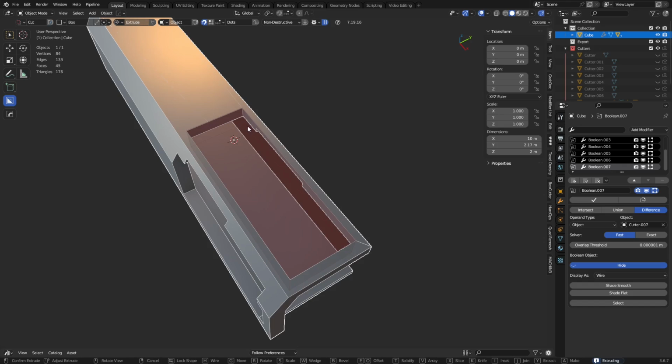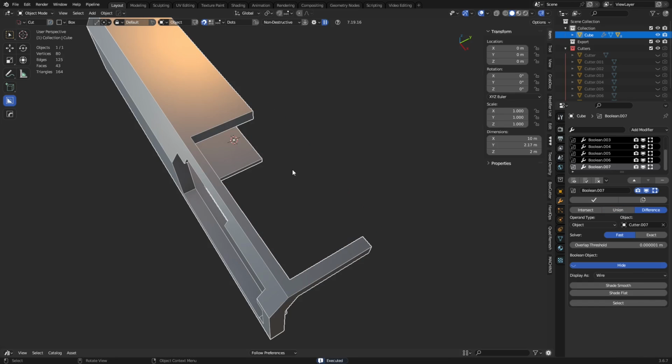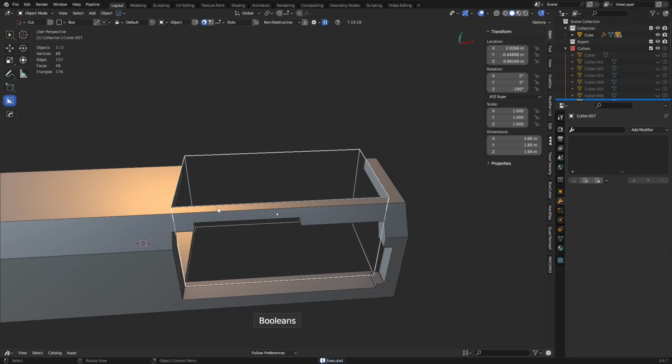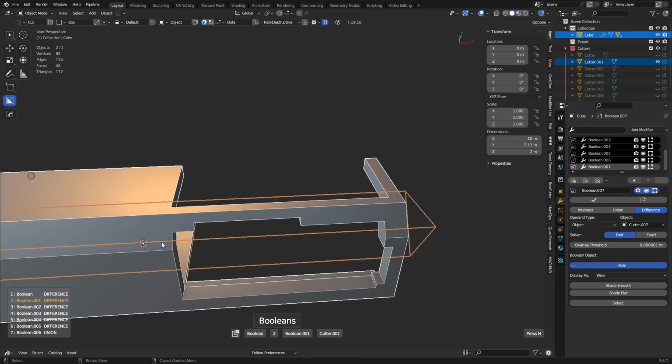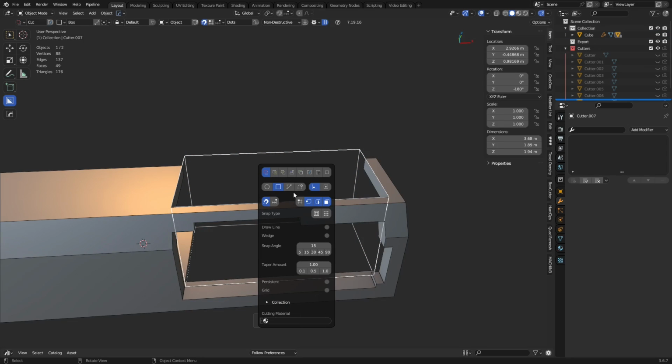What we're going to do here with this one is we could actually take, well, we won't take it all the way through, I don't think. Yeah, we'll take it all the way through. Why not? We'll change our mind here. We can bring these cutters back, hitting Q, E, right? You can mouse wheel through to find other ones. So Q, E, select this one. Use the N-gon cutter, and we're going to turn this off so that it's open.